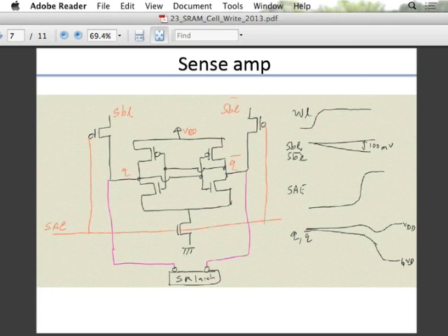That voltage will basically be at about VDD minus VT, right? Because that node is getting charged through these NMOSs. So it's about VDD minus VT. It's not fully VDD, it's VDD minus VT. But it's a common voltage to both these NMOSs.